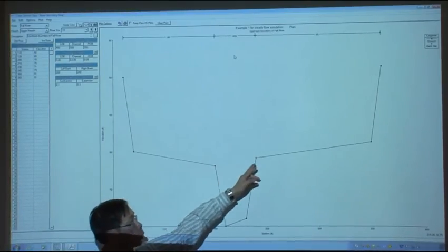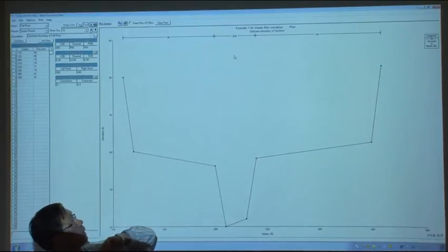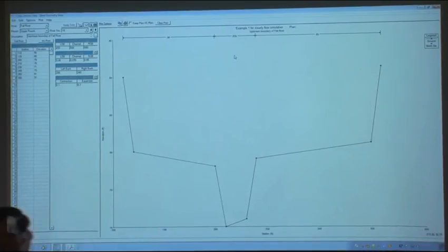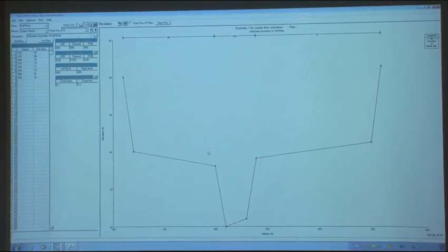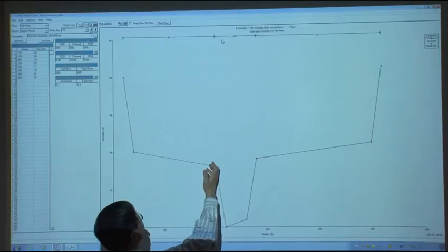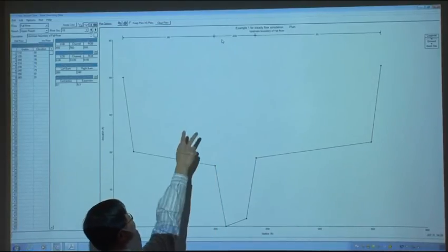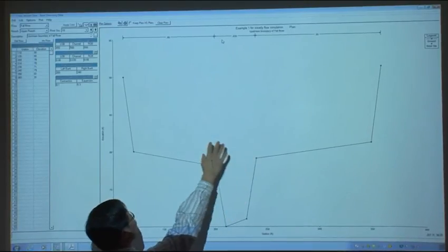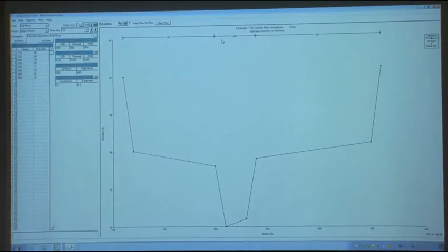These are the left and right bank stations for the main channel, and at the top they also already aligned the Manning's n values for you, exactly up to these bank stations. Between these 2 bank stations, you have 0.035 as the Manning's n value, then 0.05 for the right overbank area.